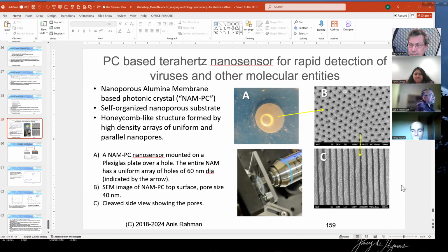The reason I asked is that making this kind of pores by chemical etching is usually not that uniform compared to lithography. Lithographic techniques are relatively a lot more uniform and maintain the hole diameter from one side to the other side uniformly or close to uniformly. Right. Well, first of all, lithography will not be able to do this. Drilling 5 micron deep holes in alumina with lithography is impossible.